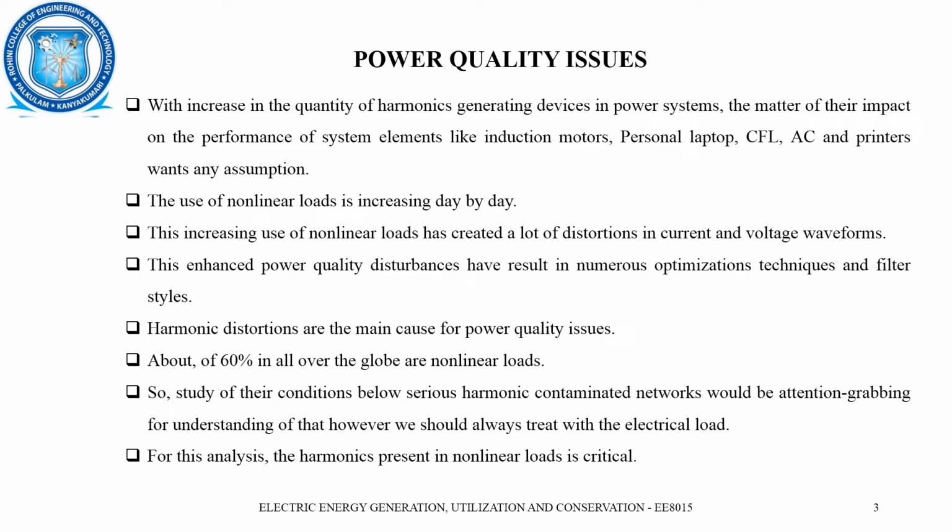The main cause of power quality issues is harmonic distortion. About 60 percent of loads over the globe are non-linear loads. So studying their conditions in seriously harmonic-contaminated networks can be a better way of understanding what is going on and how to treat the electrical load, because the usage of non-linear loads cannot be avoided.